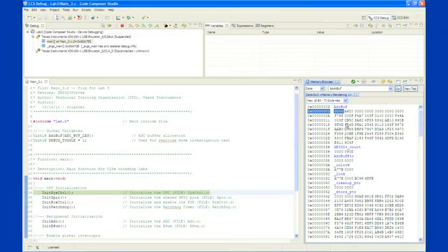We'll see we don't really have too much right now in this ADC buffer. The next thing we'll do is connect the jumper wire in the kit between EPWM1A, which is pin 17 on the header, to ADC in A0, which is pin 3.